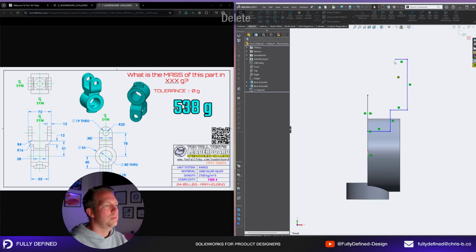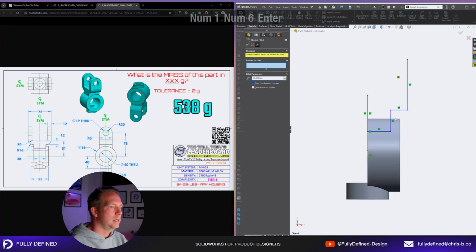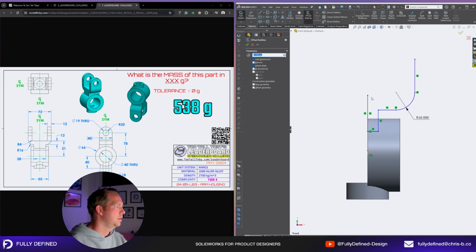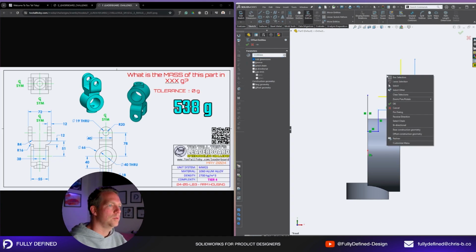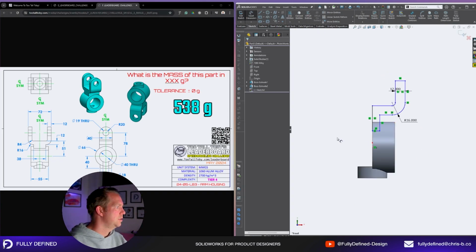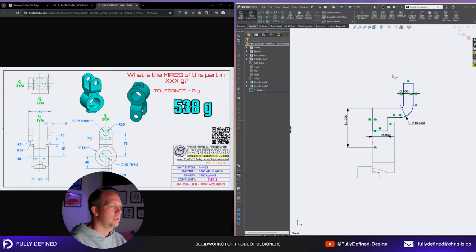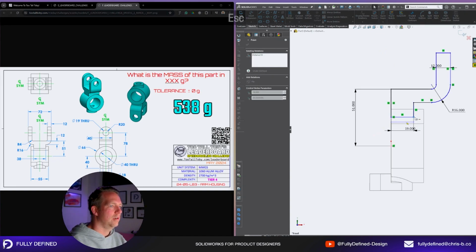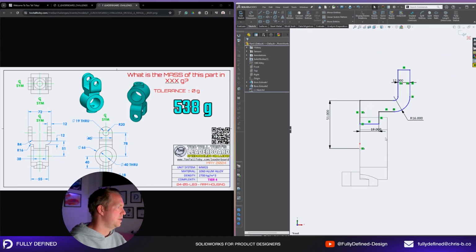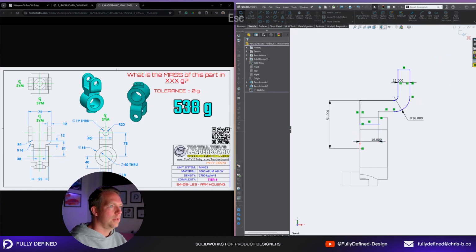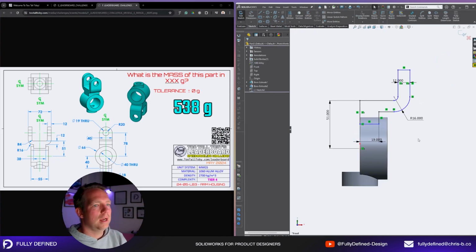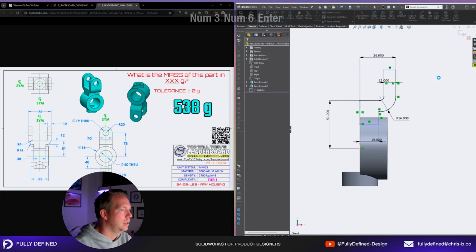Okay, so maybe that should be separate. We want to put this radius in, make sure that's big enough, or maybe we sketch it in as we go. Offset 12, I only want to do those bits. Okay, and then dimension 18, 12, 12, 12, yep, 51 there. Make sure that that's above that edge, which it is. Don't need to dimension it. If we sketch it right, that's going to be fine, as long as it's low enough. Or we could drop it there, but I don't want to have to change drawing shading view while I'm working. 36, and then the height.